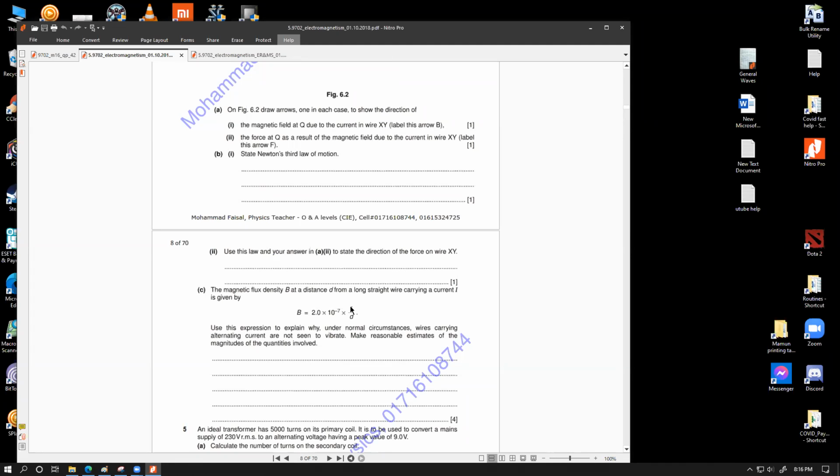So if you take 1000 watt and divide it by the supply voltage that we have in our household, about 220 to 240 volts, so 1000 divided by 220, I get about 4.5 ampere of current. So you could get 4.5 ampere current, not very typical, but that might as well be the maximum current for regular normal circumstances. So I can be considered to be somewhere around 4.5 ampere or 5 ampere, you can write, and D can be considered as about, let's say, 3 millimeter.